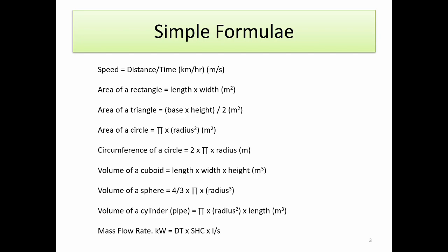For example, if we had a coil of underfloor heating pipe with a diameter of 1 meter and we had 10 turns on the coil, we could work out the length without opening it all up. So from our formula, pi times the diameter times 10 gives us 31.4. So we'd have 31.4 meters. Obviously you could round pi to 3, which gives you roughly 30 meters, which is near enough when you're measuring out.